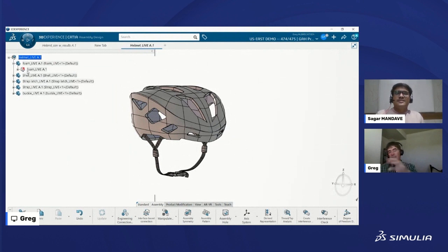So I can defeature, I can do all sorts of geometry prep here, but the actual authoring and ownership of the model, to modify the features and parameters and those kinds of things, still exists and is managed by SOLIDWORKS. And so that's kind of a nice thing to think about. So I can create my simulation geometry if I want to defeature some fillets, remove some holes, maybe add some features. I can do that all without modifying my original geometry that was in SOLIDWORKS.